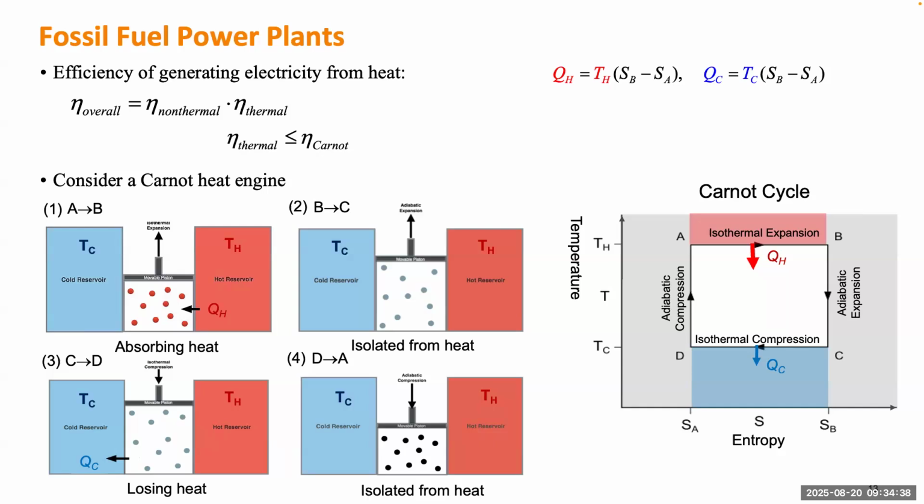So the first heat, based on this plane, we can calculate as just equal to the high temperature multiplied by the change of entropy. The second will be the low temperature multiplied by the change of the entropy. So the difference will be the work. If we tell in which direction the volume is changing, you tell this is expansion, this is expansion. So this is the direction of changing the volume, increasing the volume, and this is the direction of changing the pressure.